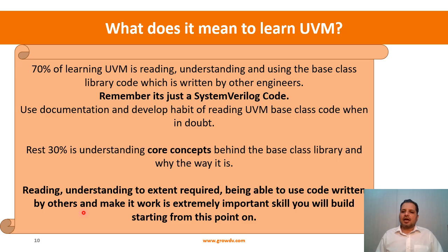If we had done it in our own way, then you would have to grep for fork and find out which components are forking off the thread and then follow them, right? But now you don't need to worry about it. Any class that's present in their test bench that's extending a UVM component, you know that it's an active component. It became very clear, right?